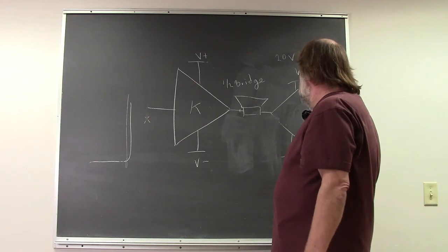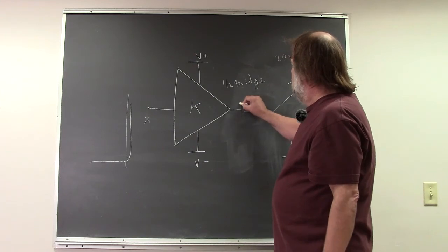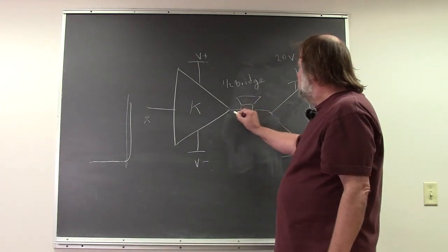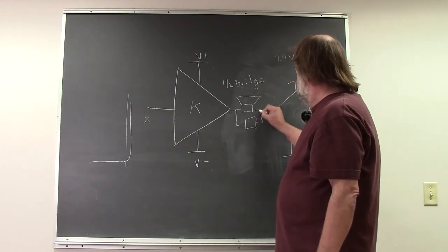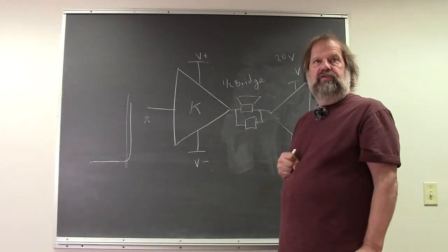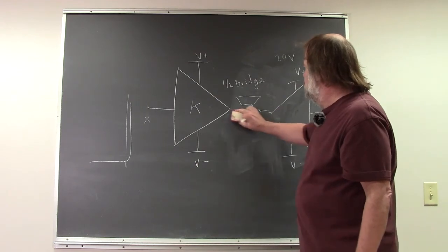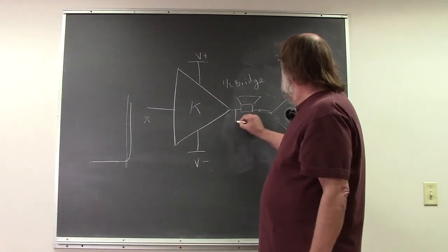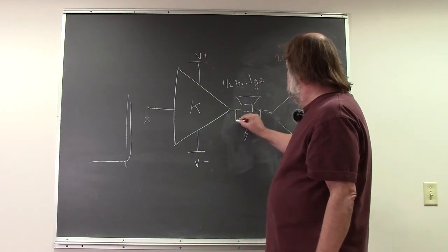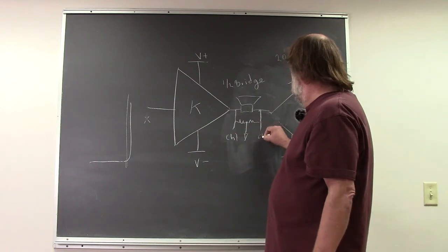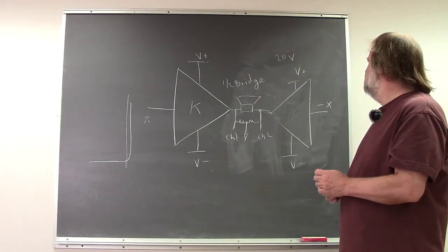Also, on the little oscilloscope measurement that I told you about, how do I know, if it's a bridge system, how do I measure it? Well, your oscilloscope might not really want you to go from here to here across the thing, because it may not be happy with the ground side connected to a hot side. So what you could do there, if you have a full bridge configuration, is put some large resistors here, tie that to your scope return, to channel 1 here and channel 2 here, and subtract the two. And that's a trick that you could do for the oscilloscope measurement.